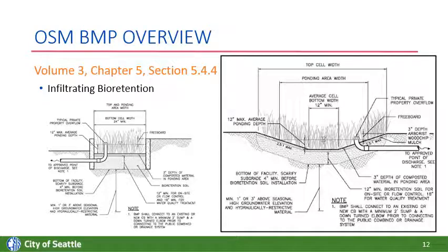So again, as you can see, this is a consistent update: if you're eliminating the overflow, there's been some additional clarification made in the manual for what is required to meet that. Clean wash drainage gravel or mulch is allowed in lieu of plants if a licensed landscape architect determines plants will not survive in shaded conditions.